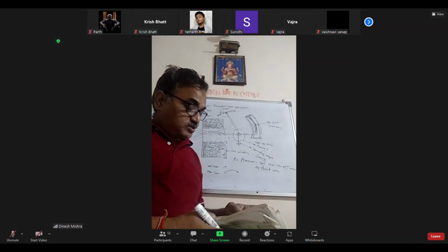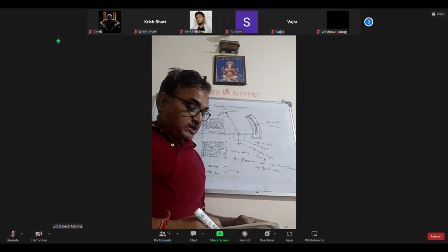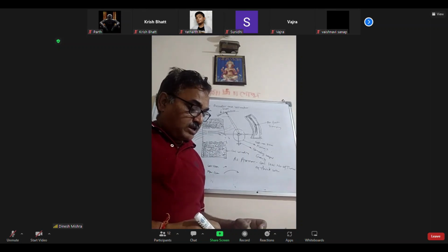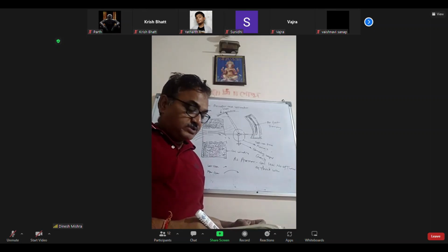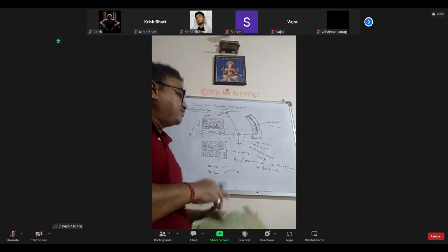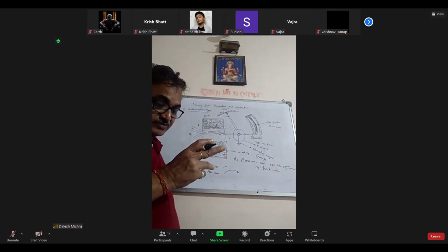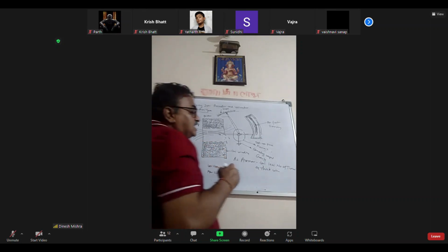So that the ammeter has a low resistance and allows the flow of maximum current, and the instrument is connected in series with the circuit. The ammeter is connected in series. It has low resistance because there is a less number of turns.